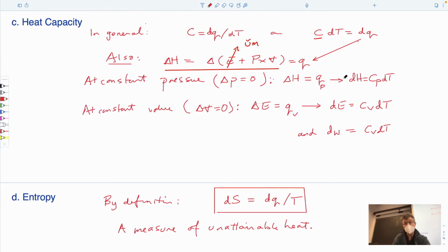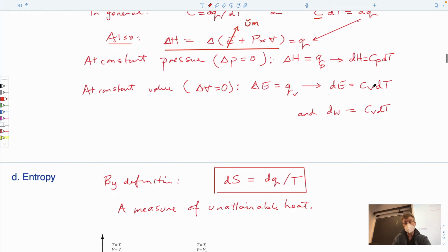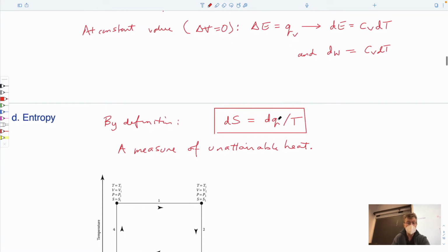So in each of those cases, we can define the change in enthalpy, which we've done already, right, for our reservoir between 2 kilometers and 10 kilometers, just as the product per unit volume of the reservoir as the specific heat capacity multiplied by the temperature it goes through. If we want to get the amount for the whole system, we just need to multiply the enthalpy by the mass and the volume, which gives us the total mass in the system, and that gives us the total amount of thermal energy that's available in that system. So we've done that already, so we won't go back to that.